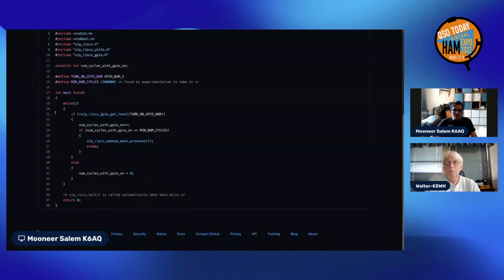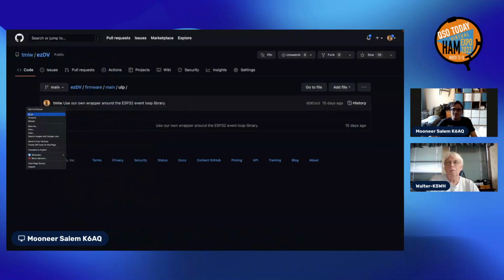So there aren't really that many external components you need to be able to just have the ESP32 go to sleep. When the main code is off, all it basically does is listen for the mode button, and if you hold down the mode button for more than a second, then it makes the main processor wake up effectively.